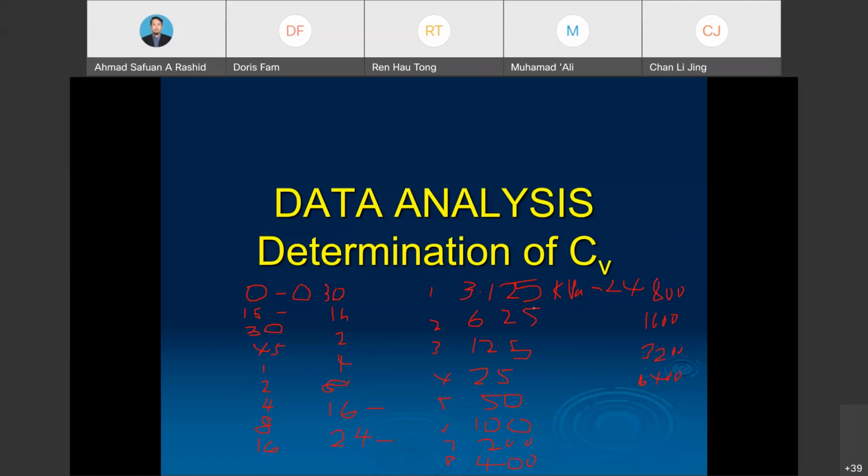Then we will have an unloading process. Later I will explain why we have an unloading process. Then we try to reload, not 100% the same steps as the loading process, but not an extreme unloading process. So we cannot go from 6,400 and jump to 400.